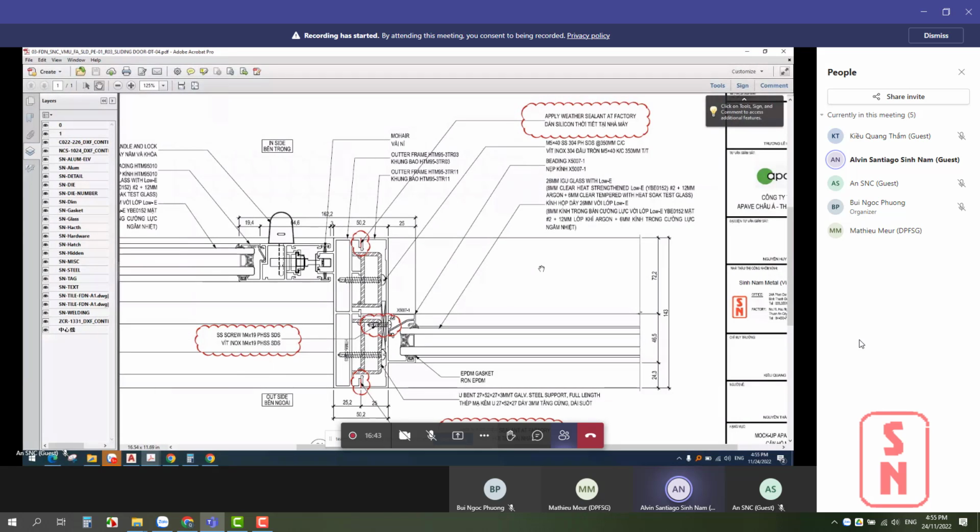We'll be fixing the steel first, and then covering it up with the right aluminum profile, and then joining them together with another set of screws. The tiny screws, the little M4 at 19, is it? Yeah, M4 at 19.